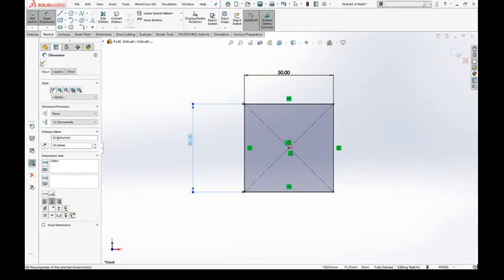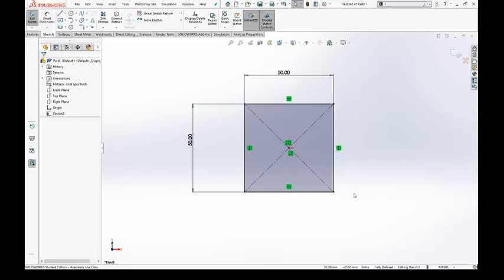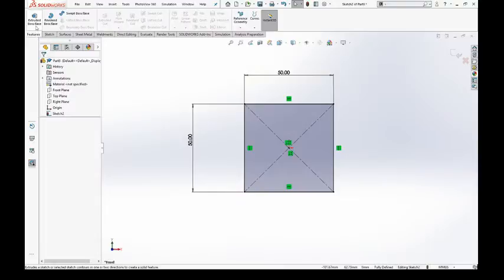From here, we can change this 2D sketch into a 3D object, and it's very easy to do. What usually happens in SolidWorks, no matter what you're designing, is you start off with a sketch and turn that sketch into a 3D object. So we've been in sketch mode and we're now going to transfer into the features tab. I'm going to left click on the features tab and choose this first icon within the ribbon, which is extruded boss base.